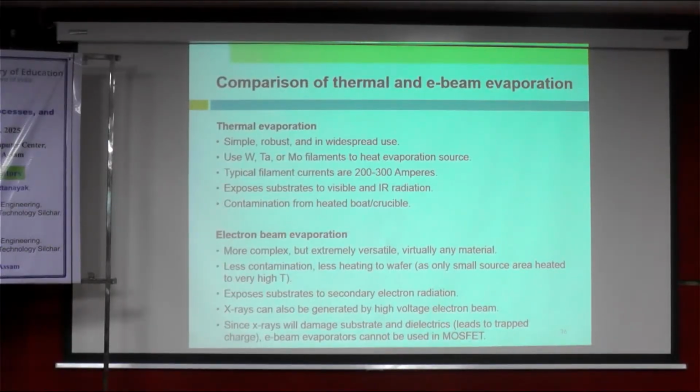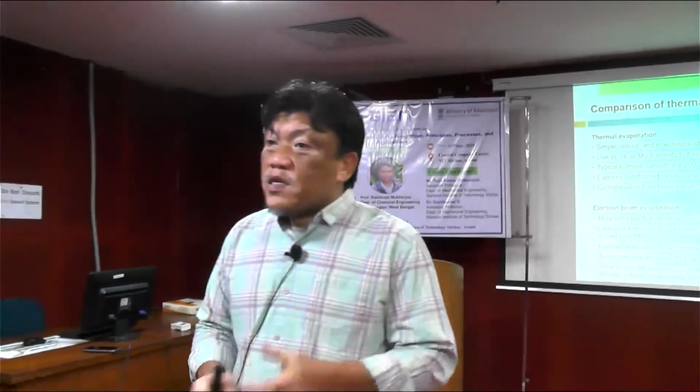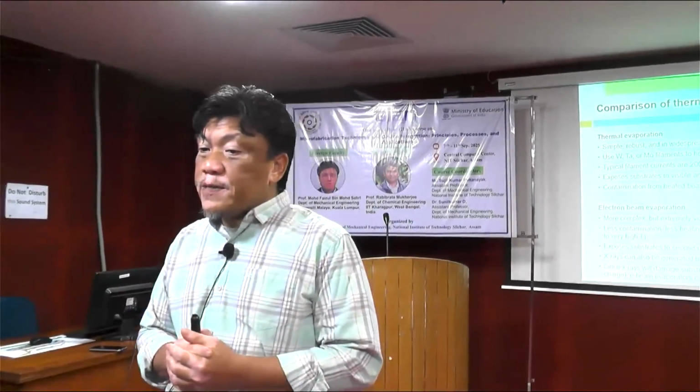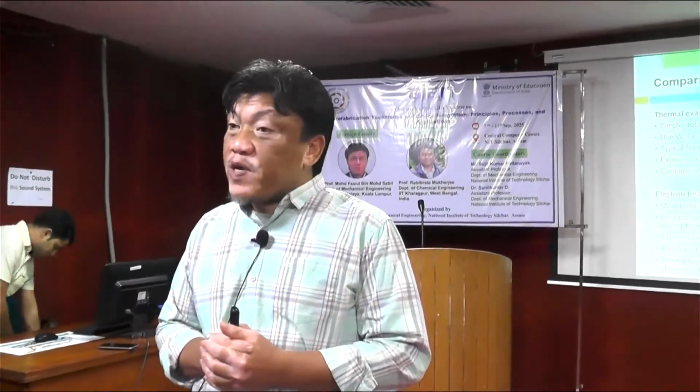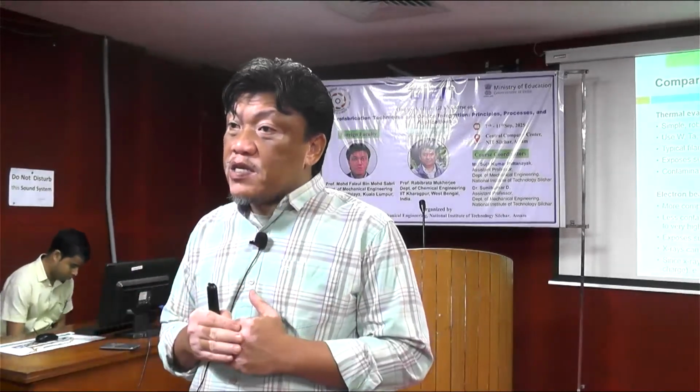Yes. Vacuum is related to the quality of the product. For PVD, vacuum is placed in the vacuum chamber. Is vacuum related to the quality of the material? Yes, to a certain extent. That is why in evaporation, it is less vacuum in comparison with sputtering.